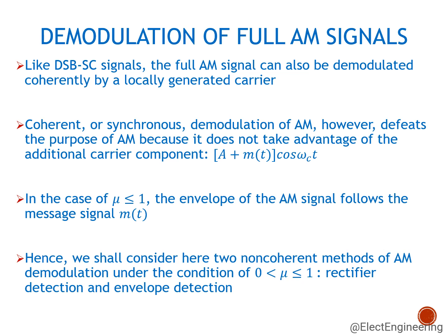Now, like DSB-SC signals, full AM signals can also be coherently demodulated. This coherent demodulation works for almost all the modulation schemes. But as we have discussed, coherent demodulation defeats the purpose of full AM, because it does not take advantage of this additional carrier that we are sending.